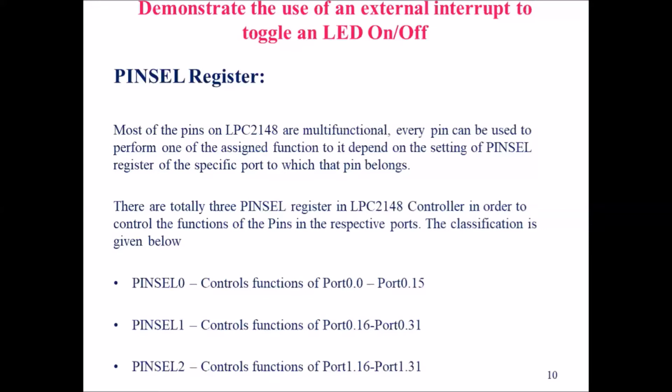So the corresponding function will be selected by the pin select register. Let's see how the function will be selected by using the pin select register. Before that, let's see some theoretical concepts about it. Most of the pins on LPC2148 are multifunctional. Every pin can be used to perform one of the functions assigned to it, depending on the setting of the pin select register of the specific port to which the pin belongs.